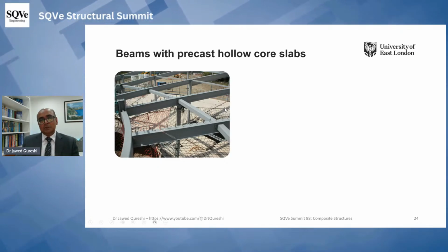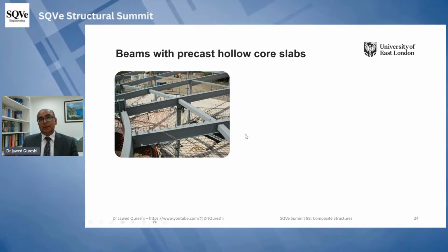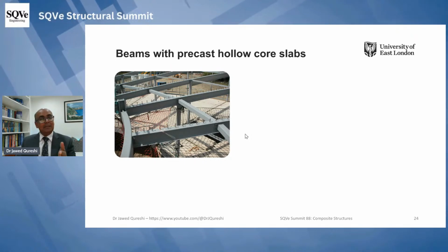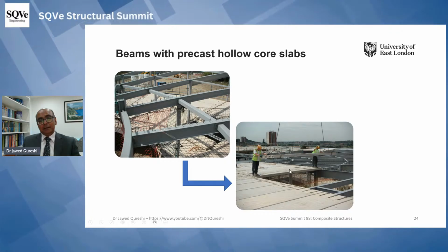But intermediate beams don't need to be connected, and we call this configuration the main beam and tie beam configuration. And the configuration that we use in the case of profile sheeting slabs, we call the secondary beam and primary beam configuration. Now here we bring cast units on top of the beams.